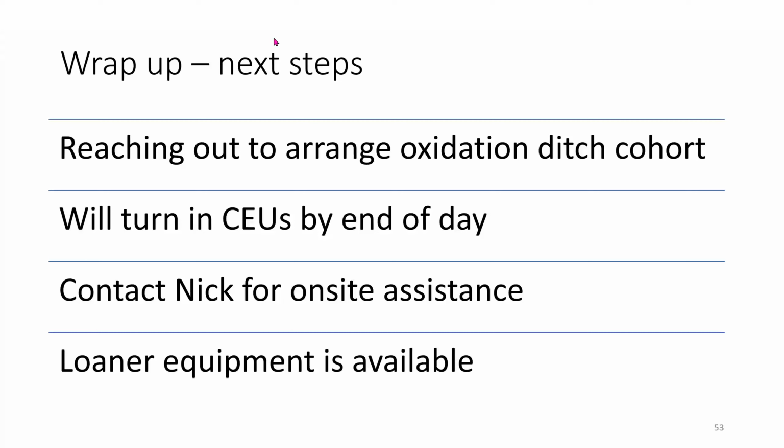So that's the answer, and that's not a place any of us want to be, where we have an aeration basin with an ORP of 0. Either that or your meter's broken, which is what we would hope be the case. But so if a toxin would come into your wastewater, for example, kill your mixed liquor, your DO would actually go up, or your ORP would go down.